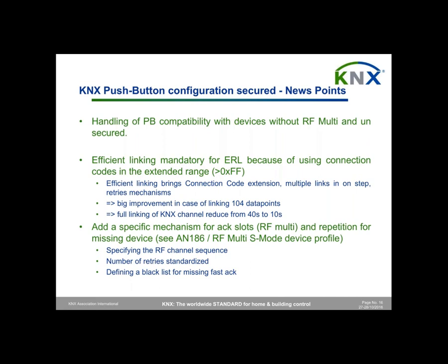The sensor will send the telegram, wait for the acknowledgements, and if they are missing, will send up to 3 retries of the same telegram to get an answer. And this will be the case every time it wants to send something to the device. So it's not a good solution for the duty cycle problem.